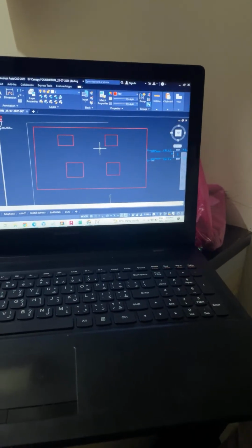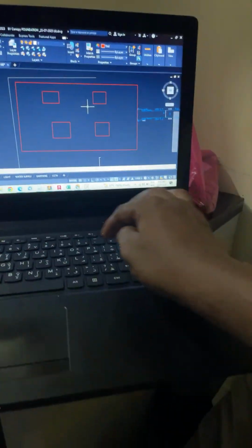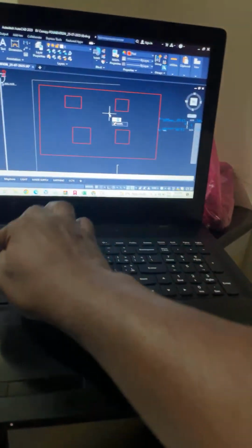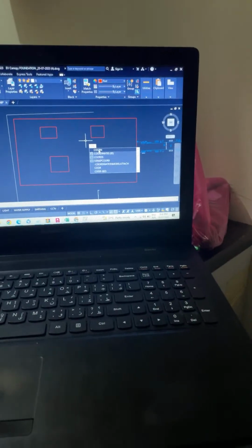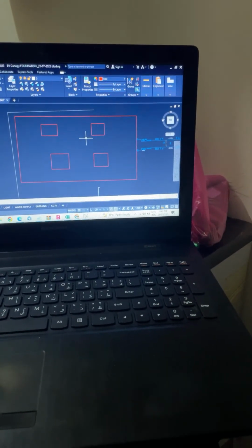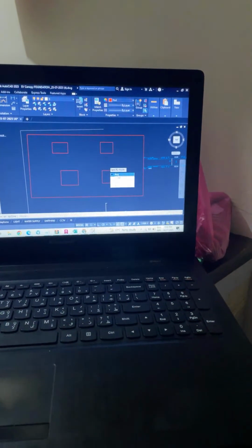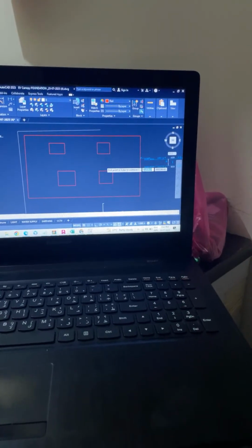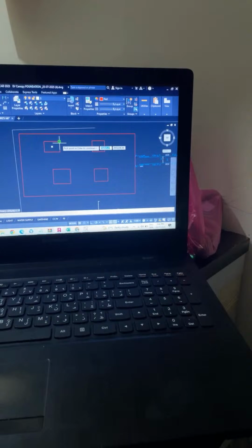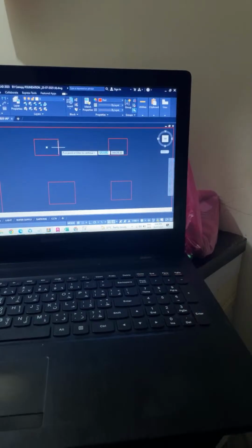Now take the coordinates. Use the application short form COORN, and see, the window came here. A pull down menu came here. Take these coordinates, name COORN, and use it. See, now one more pull down menu came here. The specification is pick points, block, polyline, or whatever you want. You have to take pick points. Okay, go to your column points and click the corner, 1, 2.